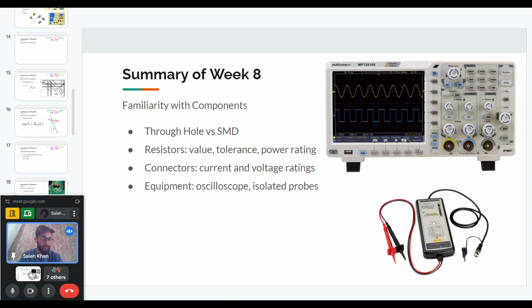But in power converters, when you want to measure multiple voltages, these voltages may not necessarily have the same ground. For example, if we have a half bridge and we want to measure the drain to source voltage of both of the switches, then the ground of these two measurements is not the same.